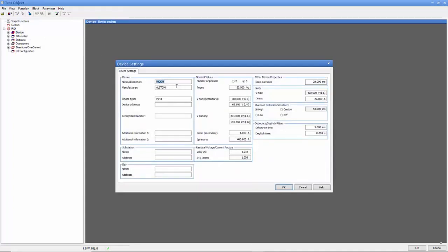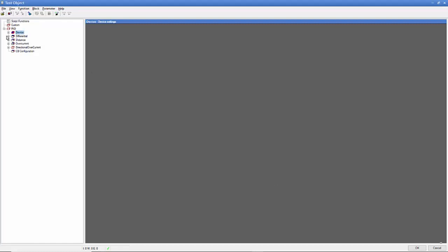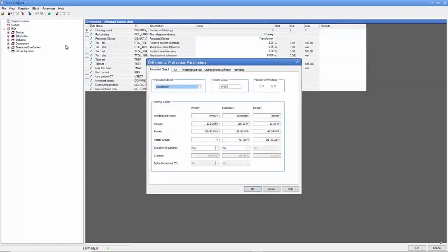Here, this is the general information before reporting. 3-phase for sure, 50 hertz. The primary side voltage, line to line, line to neutral, and the same for the secondary of the VT. If it is connected or applicable, it should be fed here. The CT ratio, and the maximum limit of current and voltage.